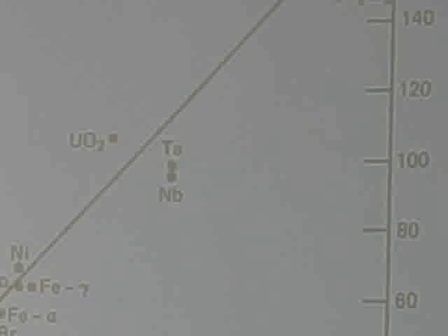So this is the activation energy for creep. This is the activation energy for self-diffusion. And you can see over lots of materials a very good correlation between activation energy for creep and self-diffusion. So it is a diffusional process, as atoms are moving around at the grain boundaries and changing the shape of the grains, basically. So if you started out with all equiaxed grains and you put a stress on it, now the atoms are going to move to the tensile stress direction and away from the other direction. Now you're going to get elongated grains. So it's just a diffusion phenomenon.